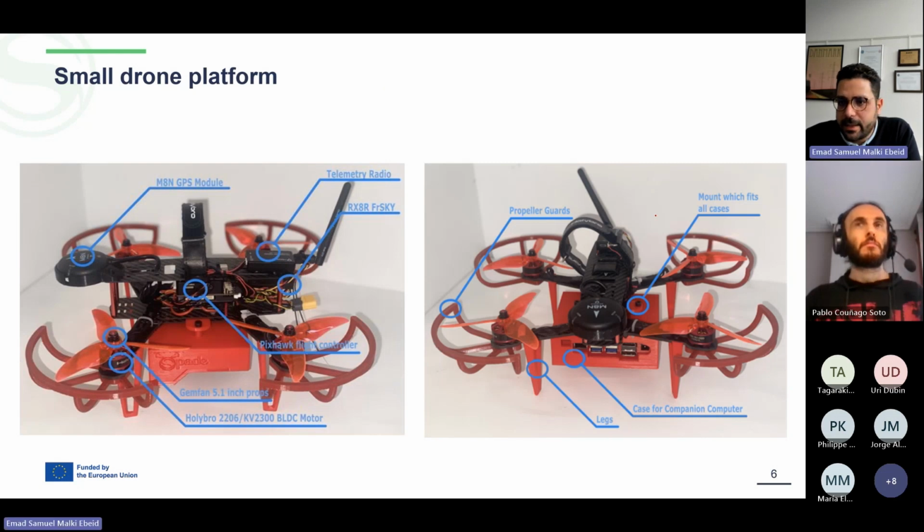Yeah, and that is the explanation of the drone and what is inside, and it has the GPS receiver, telemetry, radio link, and this radio link is for the transmitter. And at least in Denmark, it is mandatory that each drone has its own radio link, so you always have the upper hand to terminate the mission. So if I have a swarm of 4 drones, I would expect 4 ground operators, each one has a remote control to terminate the mission if something goes wrong. And usually we use the telemetry radio link for knowing the status of the drone.